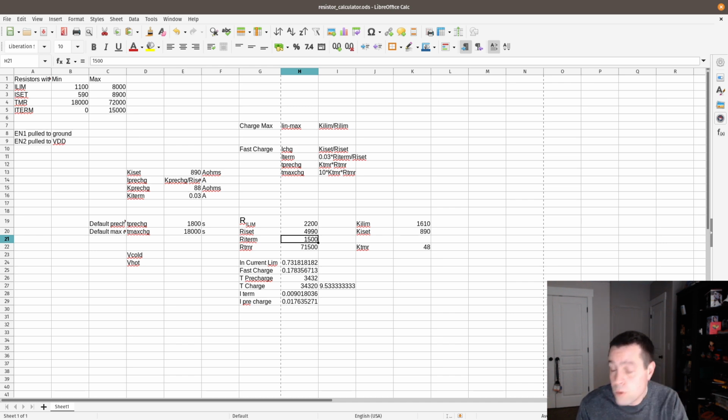Now, you can if the device requests it from the host. So when you plug a device into a USB 2.0 port that needs more than 100 milliamps to work, it will talk to the USB host and say, hey, 100 is not enough, I need up to 500, which is the max. And the host will give you that.